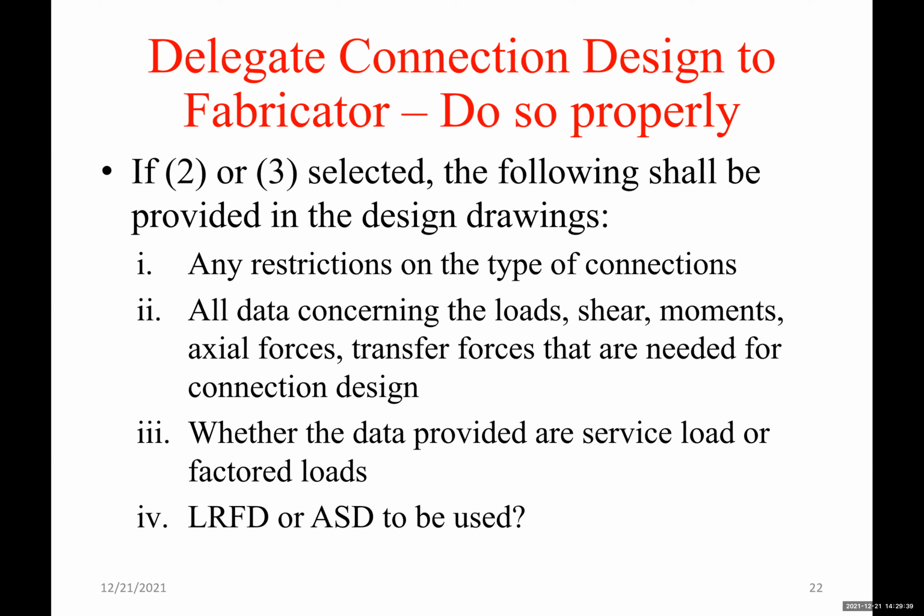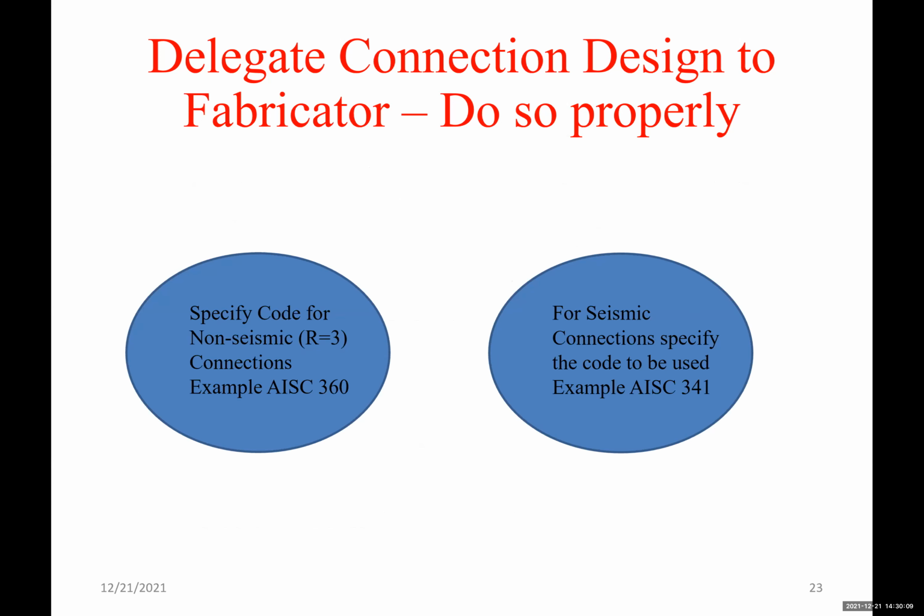All the loads should be given, whether the data provided are service loads or factored loads. This is very important. So you show reactions, you give forces, moments, axial force, in trusses, in braced frames. You need to indicate whether this is service load or factored load. Okay, and then whether to use LRFD or ASD design philosophies in the design. So that should be indicated by the structural engineer of record.